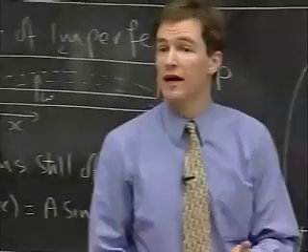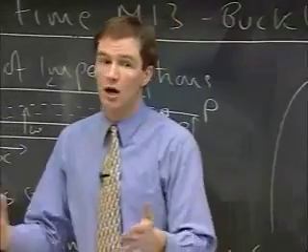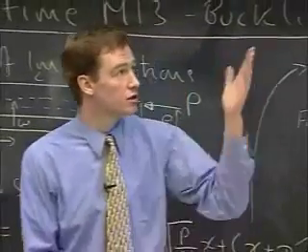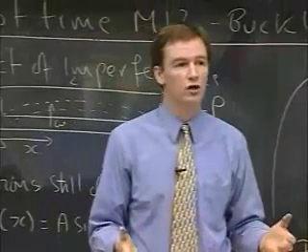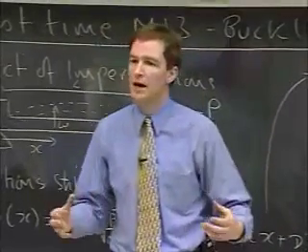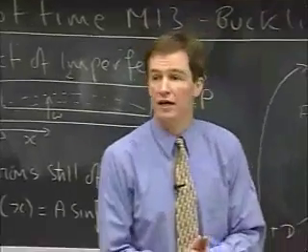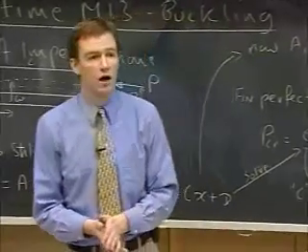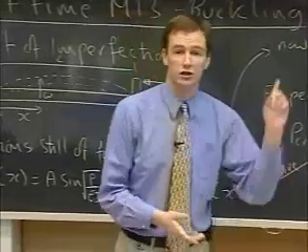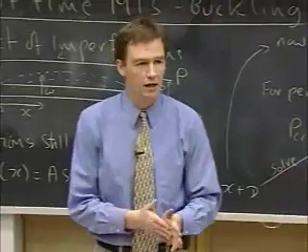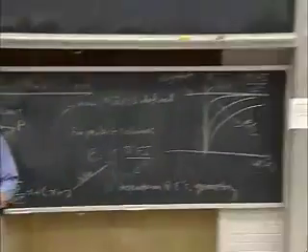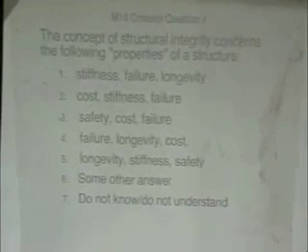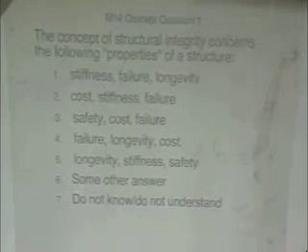It's how much deflection we are going to get for the loads we're asking our structure to carry. So that's about stiffness. We obviously don't want our structure to break into 2 pieces or to collapse on us. It's about resisting failure. And we want it to last a decent economic length of time. We want it to have certain longevity. So the correct answer is number 1. Any questions? Particularly those of you who had safety in there. Safety is an economic consideration, remember. Hard to take, I know, but we've debated at length.